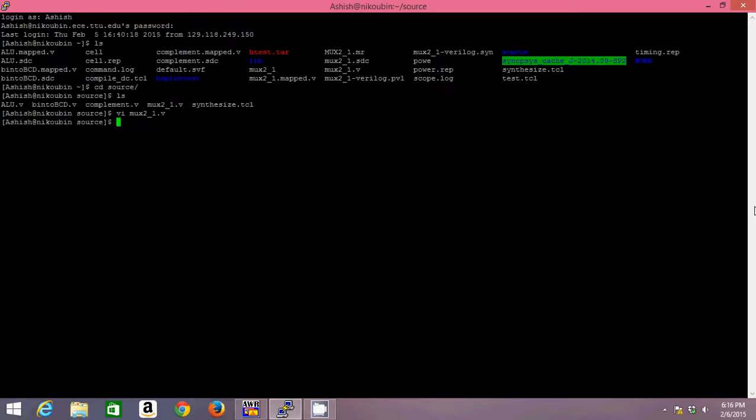So to synthesize this, I'll be making use of a script. We can also do this with the help of a GUI support, but there are many parameters to be updated for a GUI. Scripting is a much easier way. You just quote all the environmental variables at once and it will be automatically taken care of by the script. You just need to issue the script and it will automatically be synthesized or compiled.